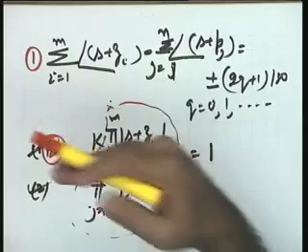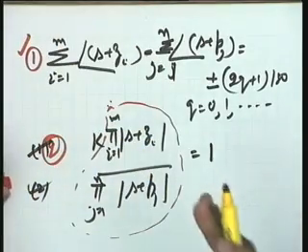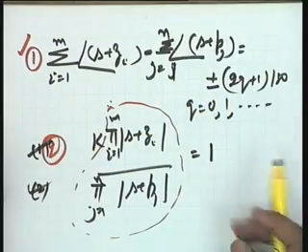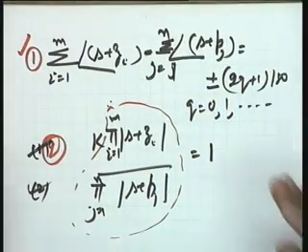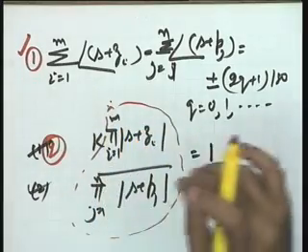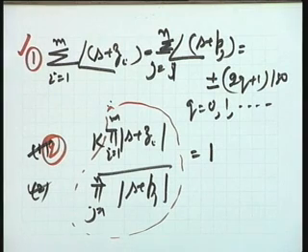So that root locus plot, which I will get by application of condition 1, can suitably be scaled with respect to the parameter k. So you can put the values of k all along the branches, so that at every point, for that value of k, your magnitude as well as angle condition is satisfied.